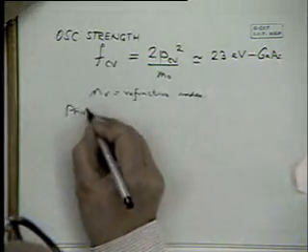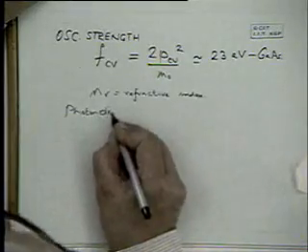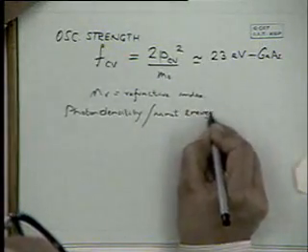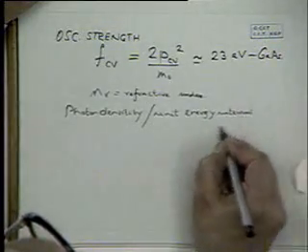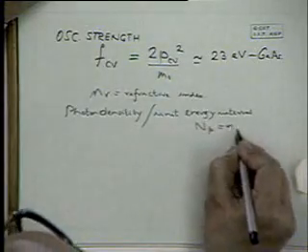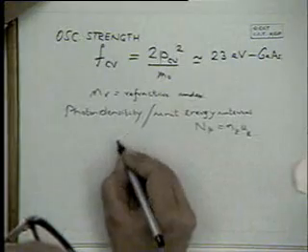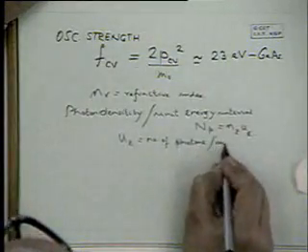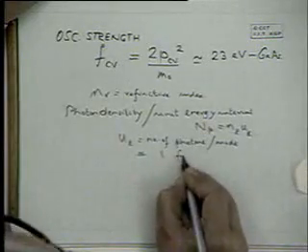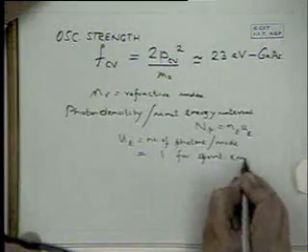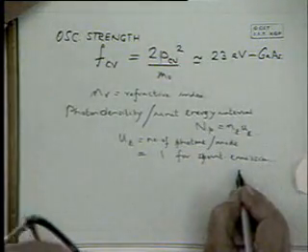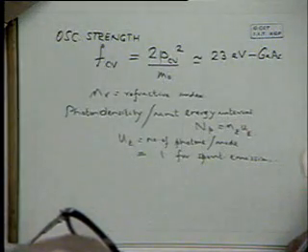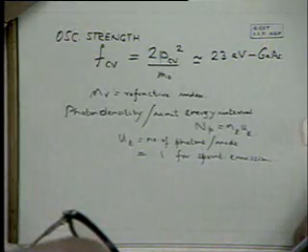The photon density per unit energy interval N_P is equal to N(E) into u(E), where u(E) is the number of photons per mode, which is equal to 1 for spontaneous emission. And the others are material constants.